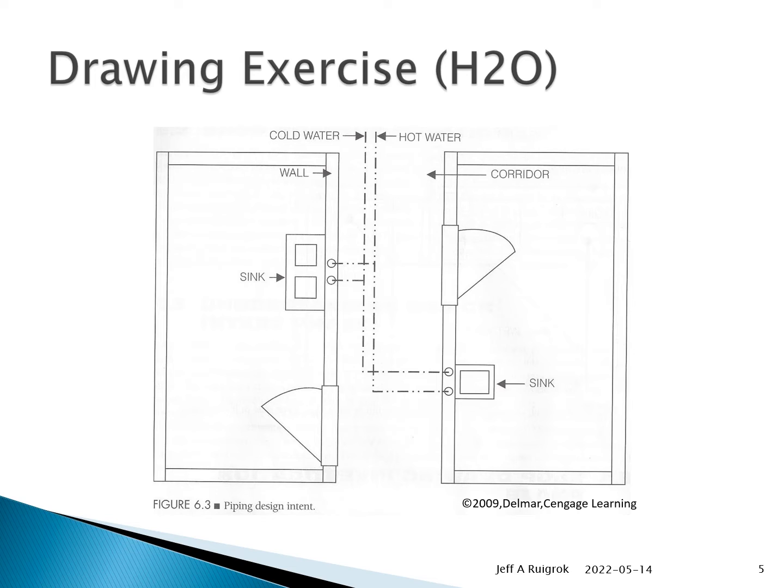These fittings here in the wall, those are 90 degrees down and 90 degrees down. So that tells you this piping runs in the ceiling. If those were 90-degree elbows facing up, that would tell you the piping runs under the floor. So keep in mind, a picture's worth a thousand words, be aware of it. The other thing to be aware of, because of the concept of design intent, it doesn't show everything. It shows the pipe going into the wall, but it doesn't show the pipe coming out of the wall underneath the sink, which you do have to have.